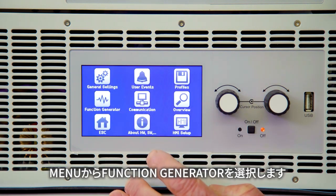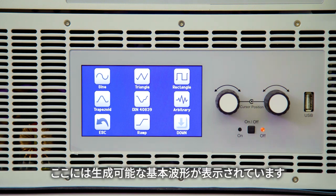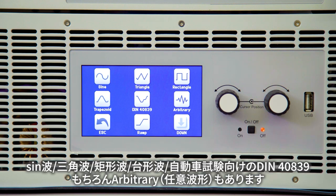Simply come into the menu and select your function generator. Here you can see we have a baseline of options: do you want to generate a sine wave or triangle? Do you want a rectangular wave, for instance, to create a pulse width modulated load profile waveform, or trapezoidal waveforms? We even have DIN standards for automotive tests. And of course, we also have arbitrary.